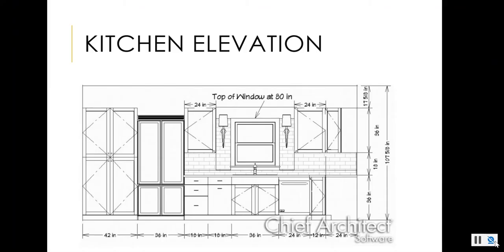Very important. So here you'll see a 42-inch pantry, a 36-inch refrigerator, 18-inch drawers, an 18-inch dresser or a drawer, and another 2 large drawers. We have a 36-inch lower cabinet with a drawer or with hinges here, a dishwasher, and then another little cabinet. They also have, very standard to kitchens, you go up 36 inches as your total counter height. Then an 18-inch backsplash and about 36-inch upper cabinets.